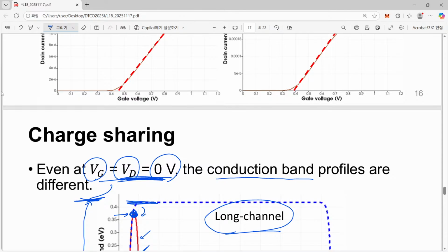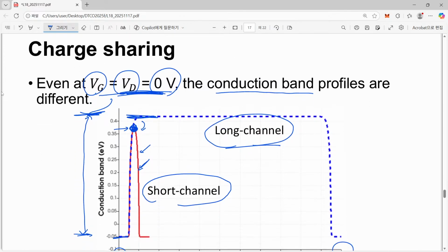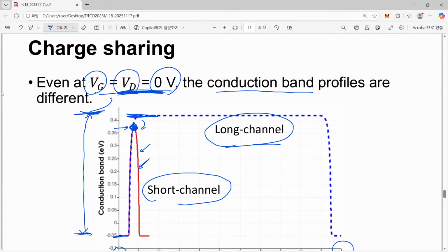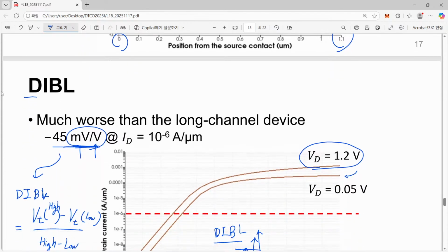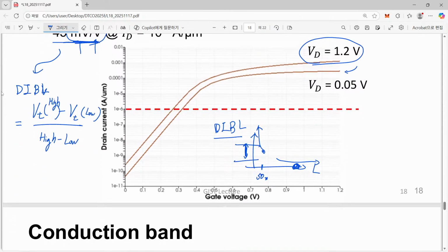The only problem is that although the device shows a certain threshold voltage at a given drain bias, it changes when the bias changes. DIBL is important for circuit designers, because they can select the length of their device when they design, but they cannot select their bias conditions, because it is given as 0 over VDD, and it is not possible for them to control this number.